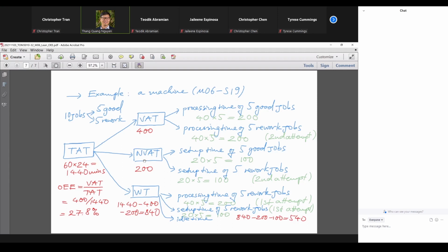The jig will help them to set up the parts very quickly. And then they drill the holes, they put the things together very fast, right? If we do it like that, then we can cut down the non-value-added time. And then if we can retrain the workers, then we can also cut down the wasted work time, right?